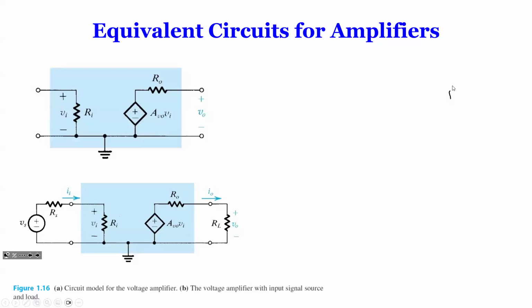But within that, what do you see? It is A times Vi. That's exactly what we did in the example. And often the amplifier has an output resistance, RO, in series. So in this case, you have input resistance, output resistance, and amplifier. And this is called, do you guys remember what the name of that symbol is? Dependent source, right? Great. That's also called a controlled voltage source.